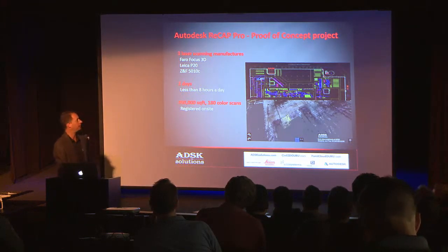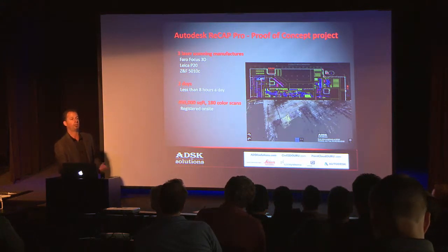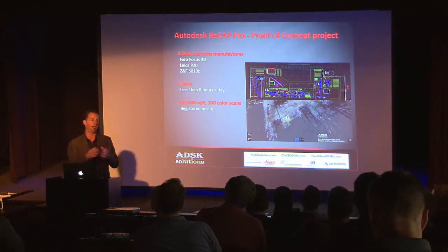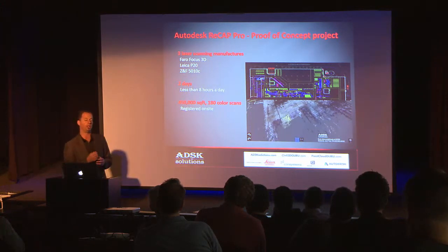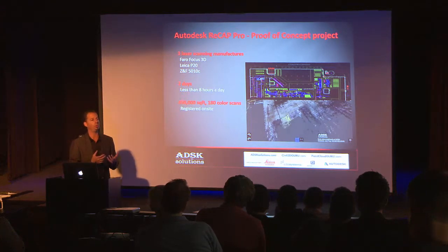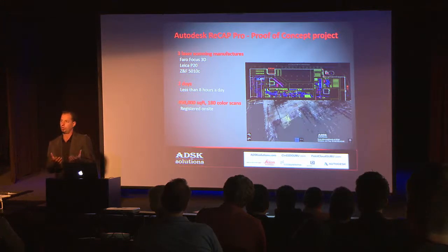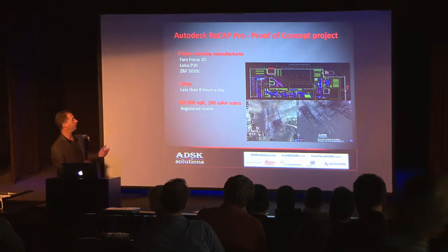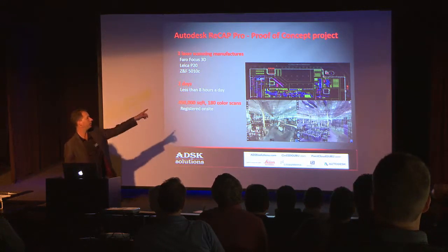What I thought was unique about this, walking in, this is all the client had, 2D deliverable of an AutoCAD drawing. We took the scan data, we just overlaid the 2D information right onto the floor plan, and you could instantly see columns that were off, columns that were the wrong way, columns that weren't even there. So it was instantly we saw that there was a problem. You can just use scan data to work in 2D. You don't have to scare the client by going 3D. Just show them it's still going to be more accurate. You have current as-builts. But by the time we walked away, this is how they were looking at their facility from their desk rather than what they had before.